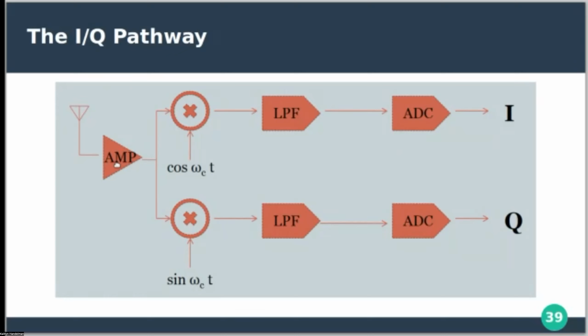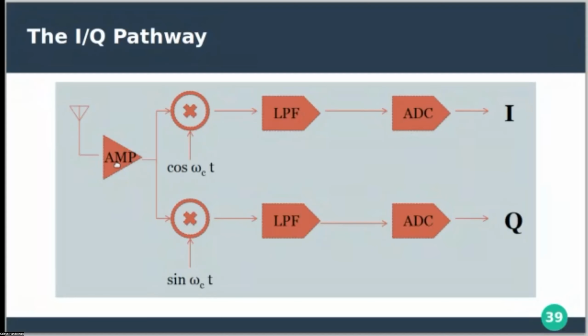So you have an in phase signal and a quadrature signal, two audio signals coming in, and you're able to transmit, like I said, 10 gigahertz, 20 gigahertz frequencies straight through your USB port, no problem. And that's how all SDRs work. Your Wi-Fi router has an SDR that's throwing things into in phase and quadrature. Your cell phone, LTE, 5G, 4G, does the same thing.